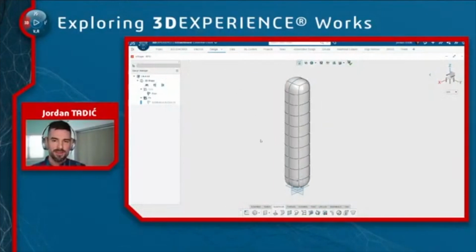That would leave you with 2 faces if we extend that out into 3D. And then the little crevice right here is another inverted, much smaller 3-point arc, so another 2 faces. If there are 2 faces for each arc, there's 2, 4, 6, 8, 10. That's how I came about choosing this. Again, you don't have to put that much thought into it, because you can always insert loops or delete loops on the fly.